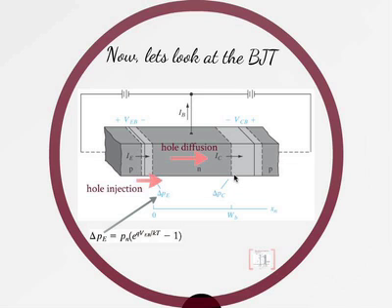But in addition to that, you have recombination, and we can solve the diffusion equation. We already did that. But we have another boundary condition that we can apply. What happens at the base-collector junction? That's a reverse biased PN junction. So that's this situation here. The base is over here. This is the collector, flipped around.